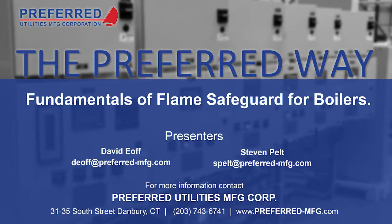So it can be a safety device from that standpoint. Good question. Preferred's representative Mario Franciscini in Puerto Rico really drove that point home to me. It's always a beautiful 85 degrees in the afternoon in Puerto Rico, but they still use a lot of O2 trim because, like you said, it's a safety device and they burn a lot of oil. So O2 trim can keep you from smoking more so than a system that doesn't have O2 trim.